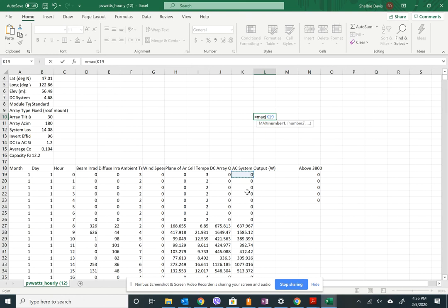So we're going to choose that inverter. After all of that, we have secured the fact that that 3.8 Sunny Boy is the one. The 5.0, that's too large. You're going to have more loss. There's no reason to purchase that. It's like having your truck idling or something.